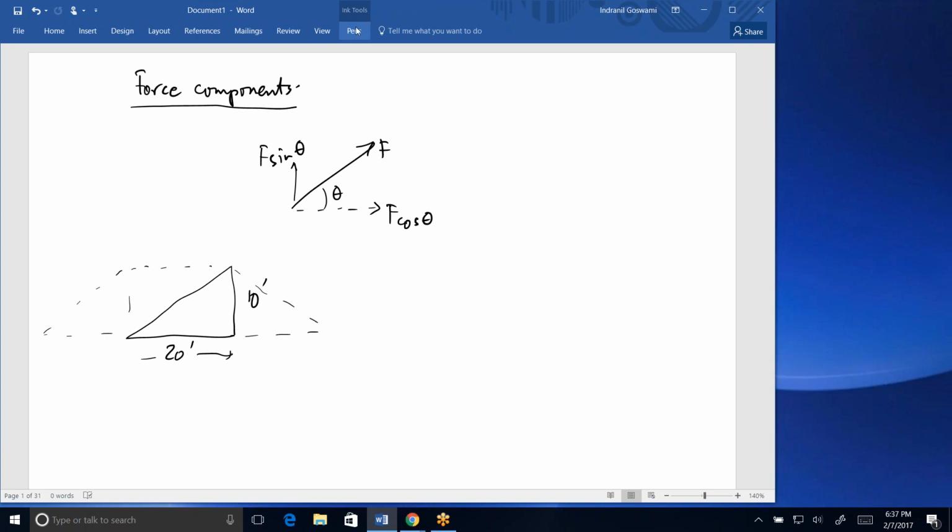But let's say you're dealing with that particular member. You're dealing with that particular force, F2, on that angle. So obviously there is an angle here, theta, and you could figure out what that theta is. Tan theta is 10 feet divided by 20 feet, 0.5, and from there you get theta is equal to, whatever, 26.6 I think is the angle that gives you a 1:2 tangent, and then you use the sine and cosine of this. But you can say that that particular line is on a 1:2 slope, so Pythagorean theorem would say this is square root of 5.